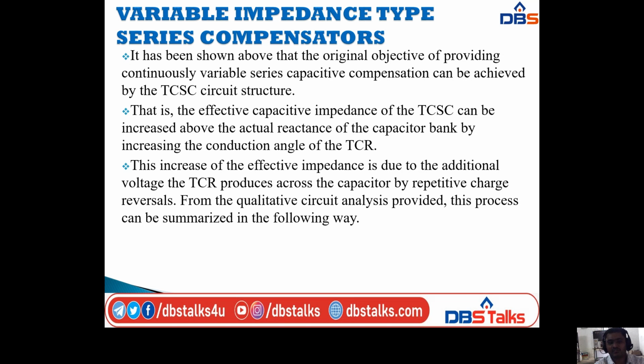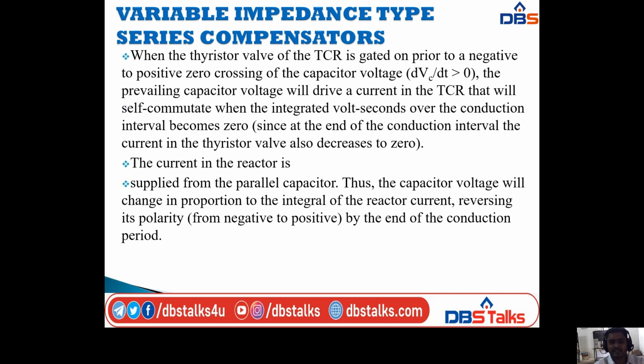From the qualitative circuit analysis provided, this process can be summarized in the following way. Firstly, when the thyristor valve of the TCR is gated on prior to a negative to positive zero crossing of the capacitor voltage, that is dVc by dt is greater than 0,